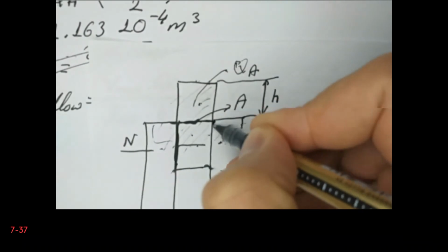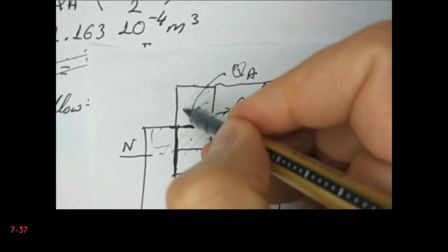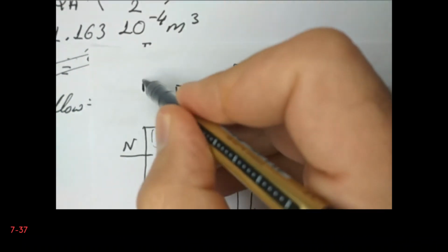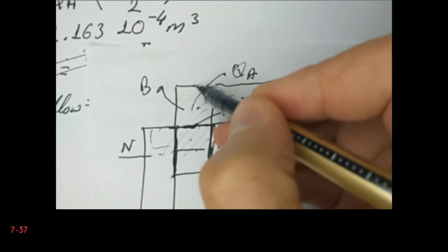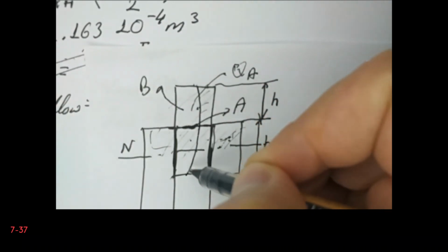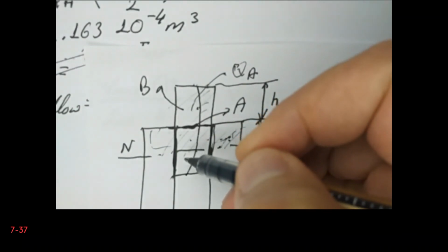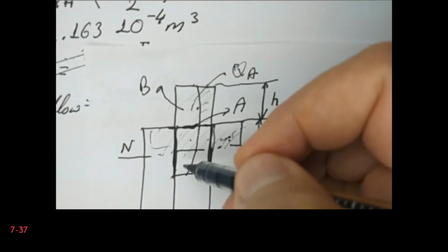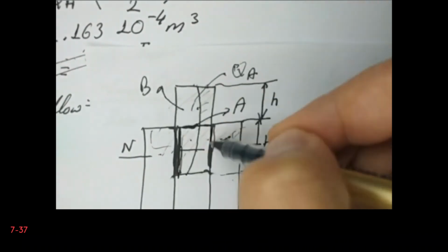So, and in fact, force carried by this center block, so let's say that this is B. Now what we need to do is to integrate the shear through this block. In other words, we need to calculate the shear flow at this interface. So we have two interfaces here, but mainly we have one block at the center, and therefore we can easily calculate the